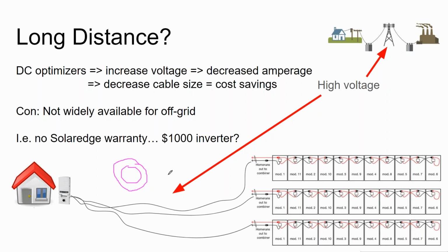And so, to some extent, when you are upsizing cable because of voltage drop, you're buying a lot more copper than you really need. You want to kind of right size it, so that a lot of cable will be rated for 600 volts or 2000 volts. Solar cable is rated for 2000 volts, and there's hardly even 2000 volt capable products out there.